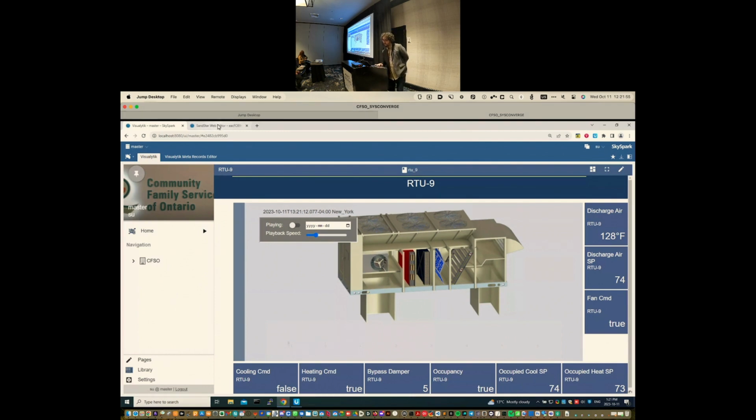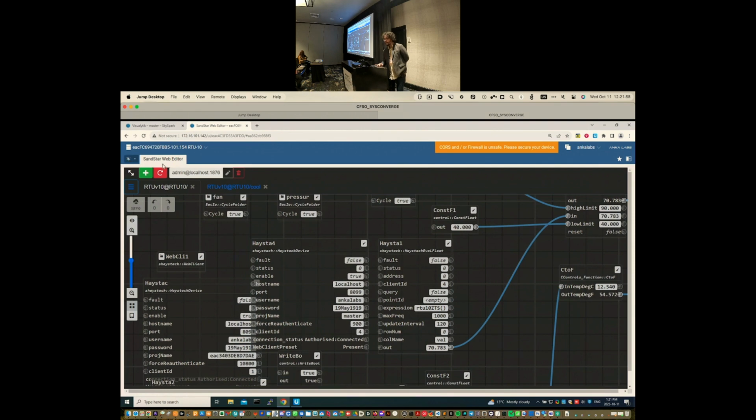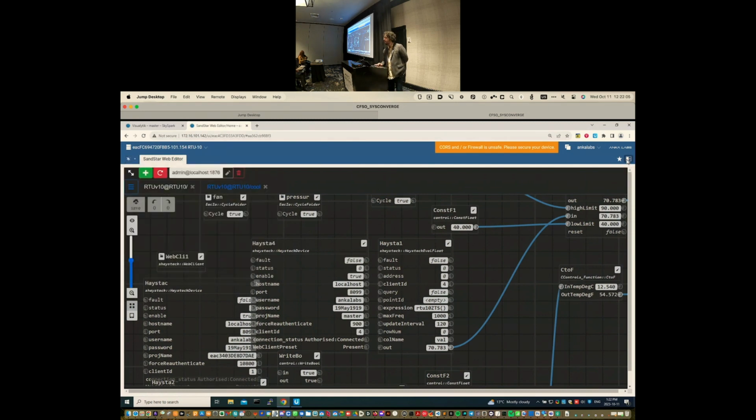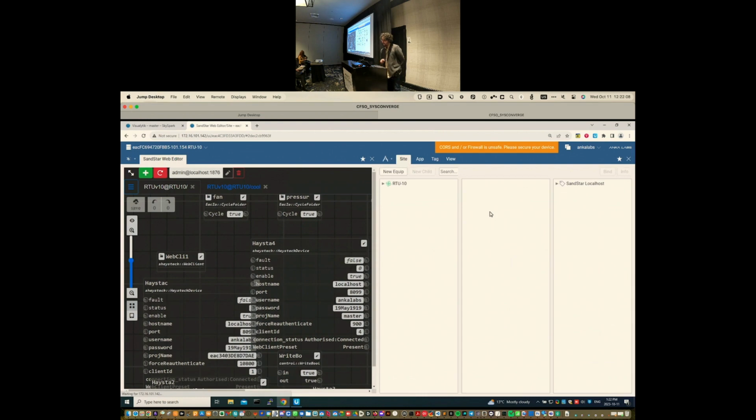Why do I say that? The only thing we need to tag to get a rooftop unit into an automation system is the site-ref tag. For a VAV, all we have to do is give the site-ref tag and the air-ref tag for the rooftop unit it is coming from. So we can literally drag and drop a VAV to a rooftop unit, and it becomes part of the network. The graphics, sparks, alarms, everything would be automatically commissioned.